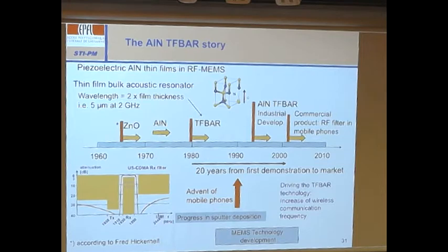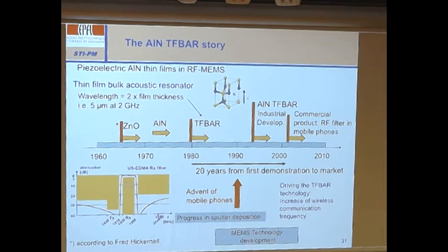So it's impossible. And people found a very good solution. These were surface acoustic wave devices, and there it's just the lithography that determines the frequency. You take a lithium niobate crystal, a piezoelectric crystal, and you make an integrated electrode system, and you define the surface acoustic wave frequency there. And so it's a very excellent solution.